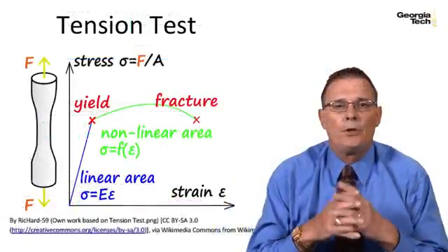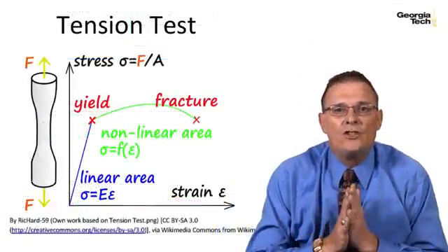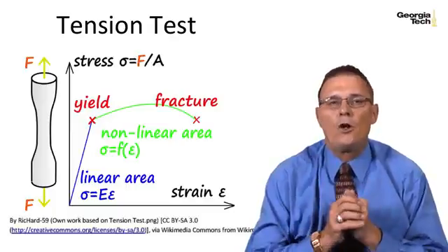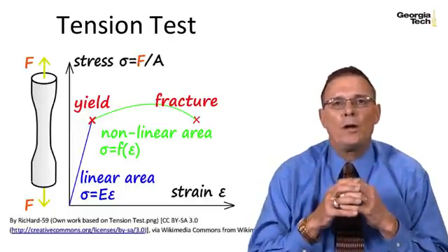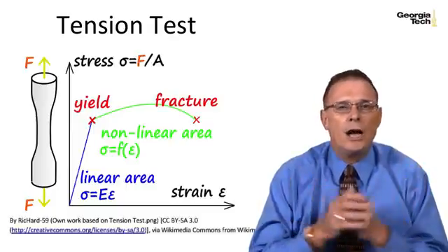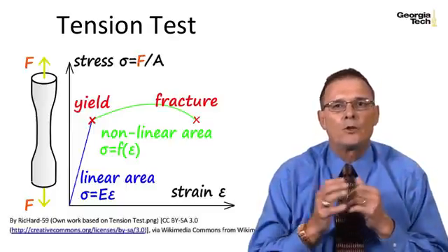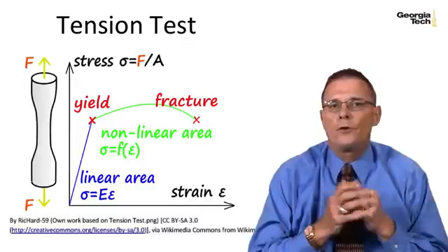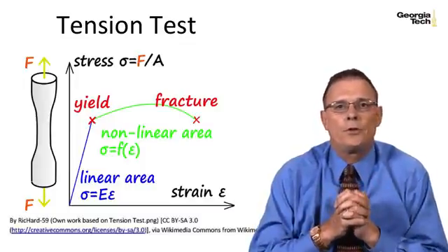To examine material properties, we can perform tension tests. In graphing the results, we will plot stress-strain instead of force and change in length. This allows for the removal of geometry from the problem and allows the results to be used for different geometrical shapes of the same material.